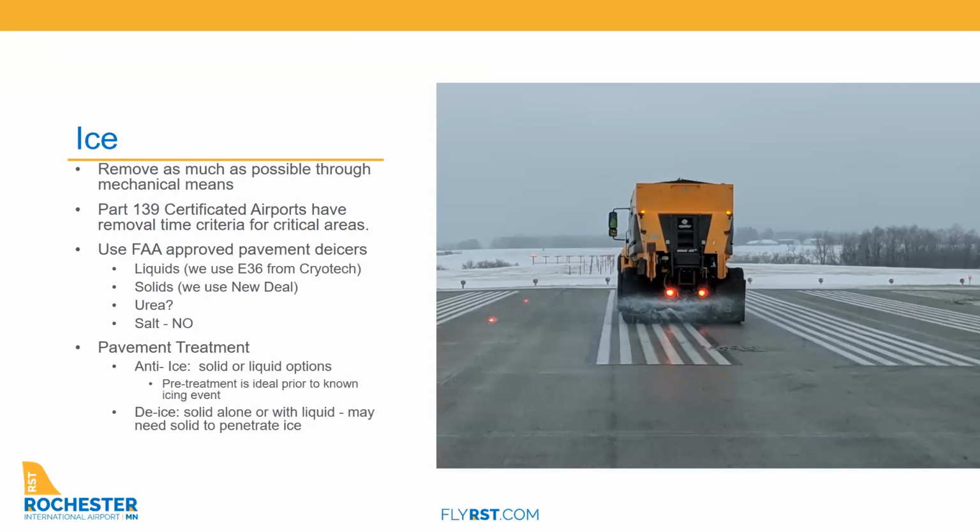We've always had ice, and now it just seems like we have more. So it's probably one of the more challenging things for an airport operator to manage. I would tell you that removing as much as possible through mechanical means, whether that's a broom or a blade, either way, anything you can take off ahead of time before it freezes is going to be better.